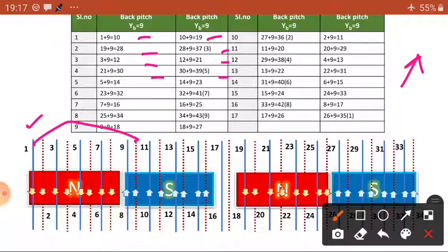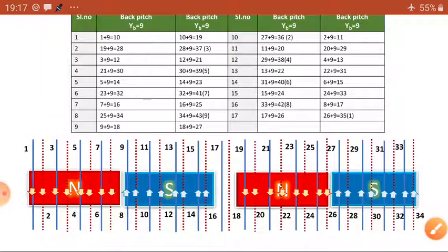Okay. Here I showed, solid one is the top conductor in slots. So top one is the solid one and the bottom conductor is the dotted one. You can see, top one is the blue and the bottom one is the red color, representing the dotted and indicating the even numbers. Okay. So in a similar way you connect based on the table. This is another step.